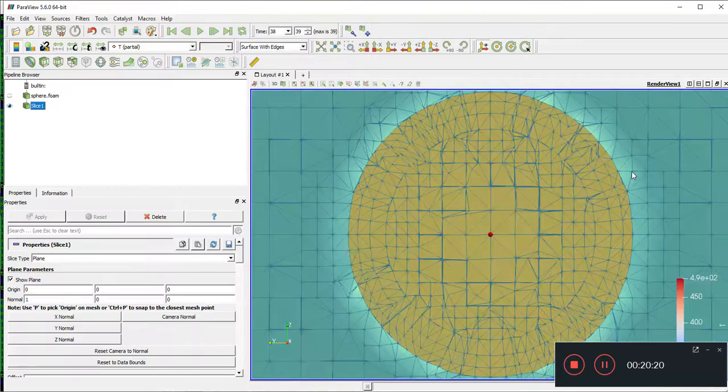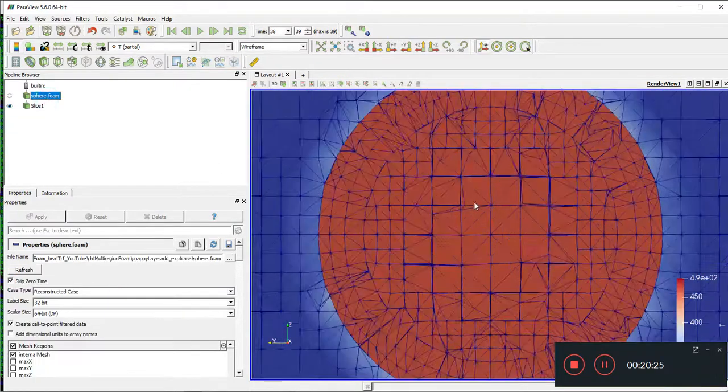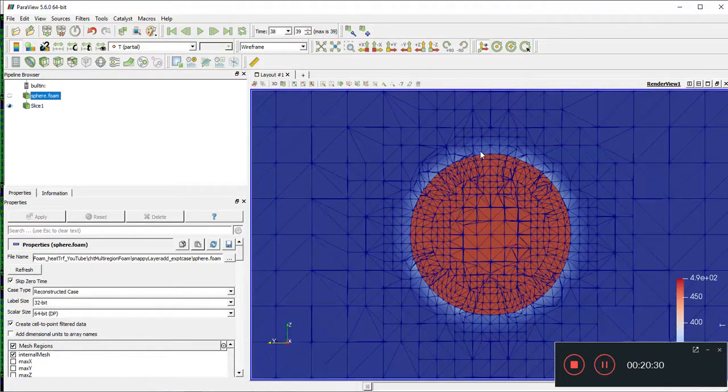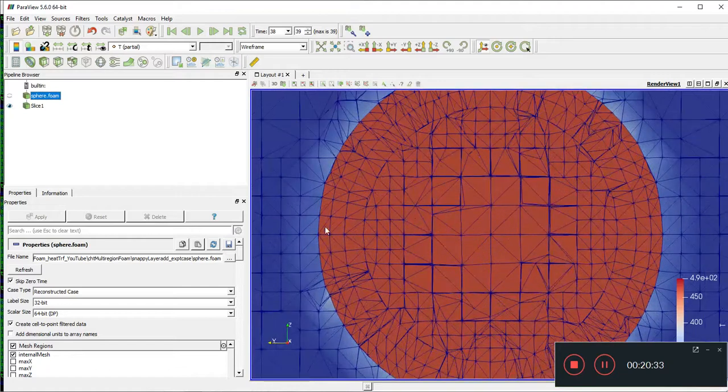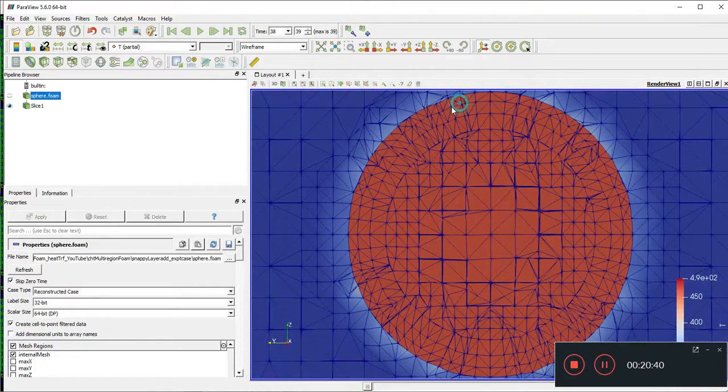Okay, and not only cancel the simulation, I'd like to also change the mesh of the oil layer. So okay, this is correct, where we have all of these meshes here, and that does help with the heat transfer coefficient. But I think we need to add layers in the oil region as well. So first things first, we want to cancel this